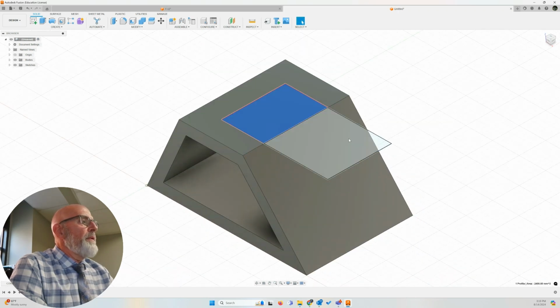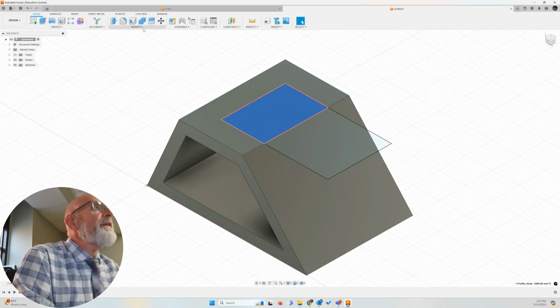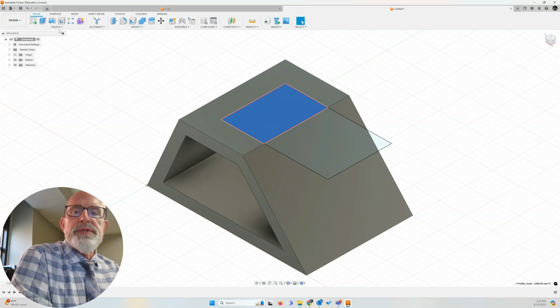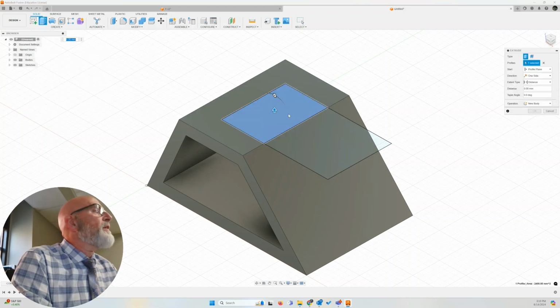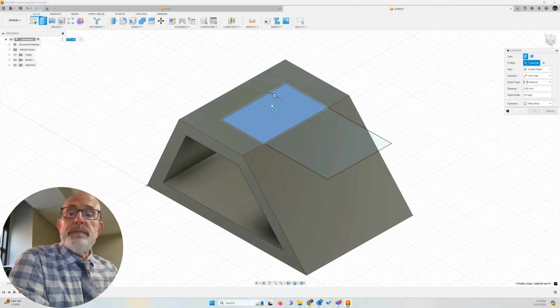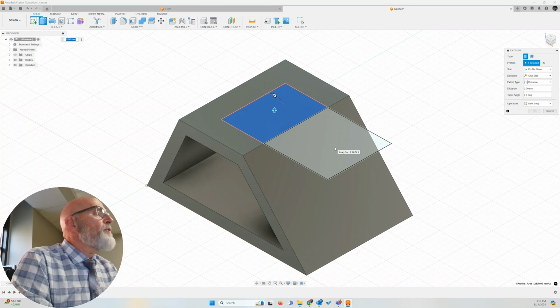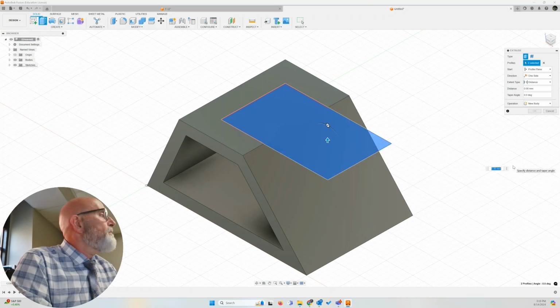We're going to have two sections on it. I'd like for it to be one enclosed, but that's not what we're going to get because of that edge. Let's extrude, keyboard shortcut of E. Here's the shortcut, select. It selected my first item because I'd already clicked on it. I'm going to select the other section of it. So I've got two items selected.